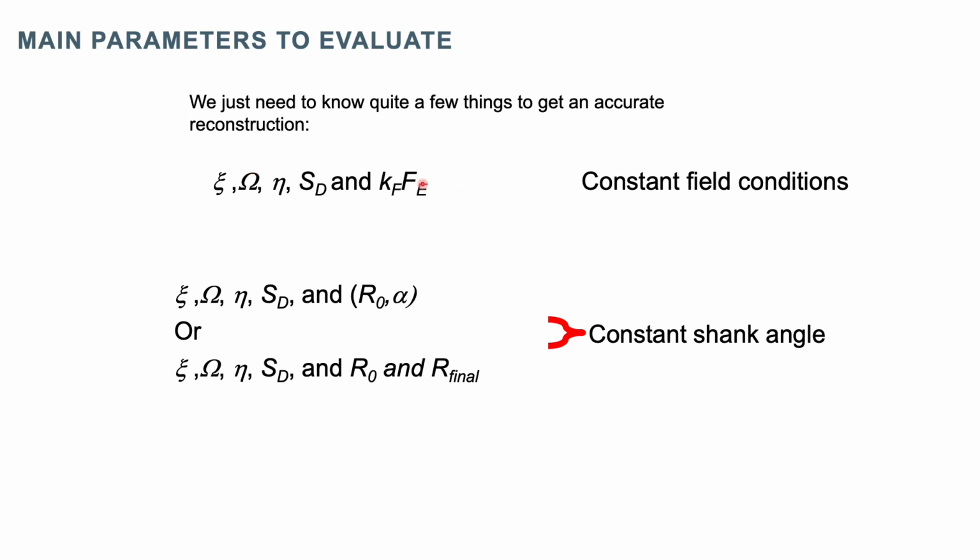And if you just don't want to use the voltage curve to get the radius, but use the shank angle because it might look better, there's still quite a lot of assumptions in there with respect to the radius and the shank angle that you're going to be using, and same thing for the tip profile reconstruction. You're imposing a radius which might not actually be right, in part because during the field evaporation process the specimen itself will change shape, and when you go from one phase to another locally radii will develop, and none of these things are taken into account in the current reconstruction protocol.